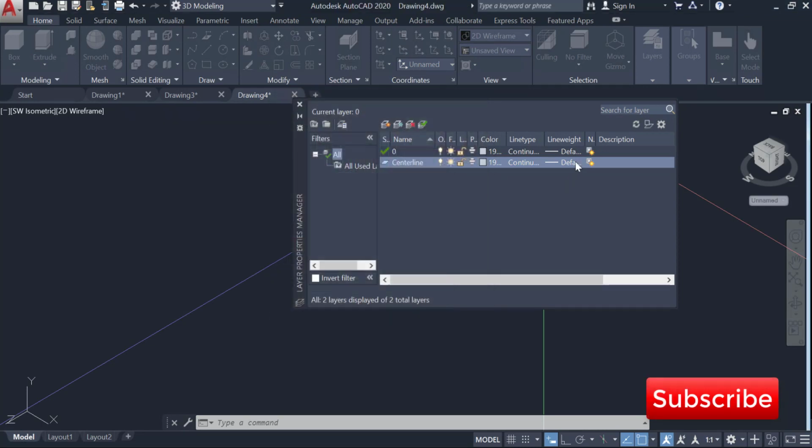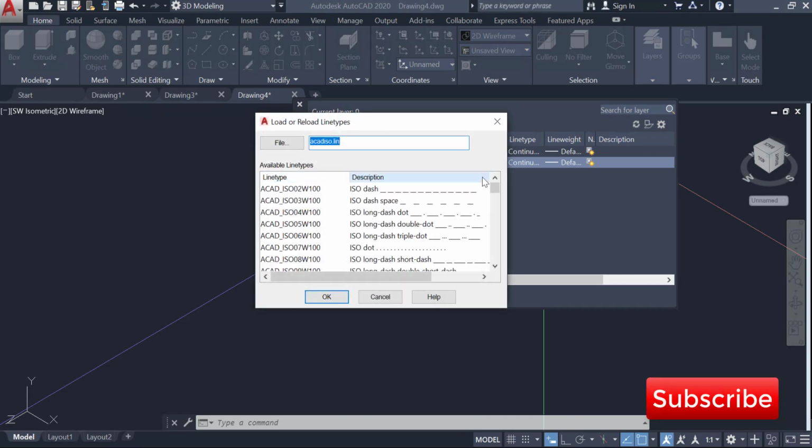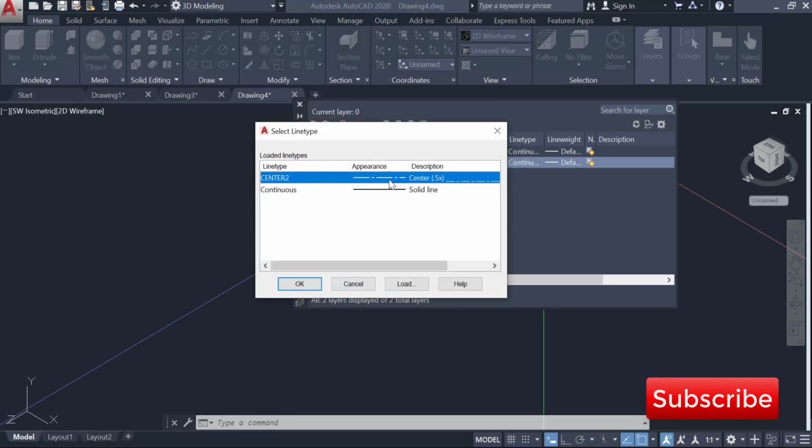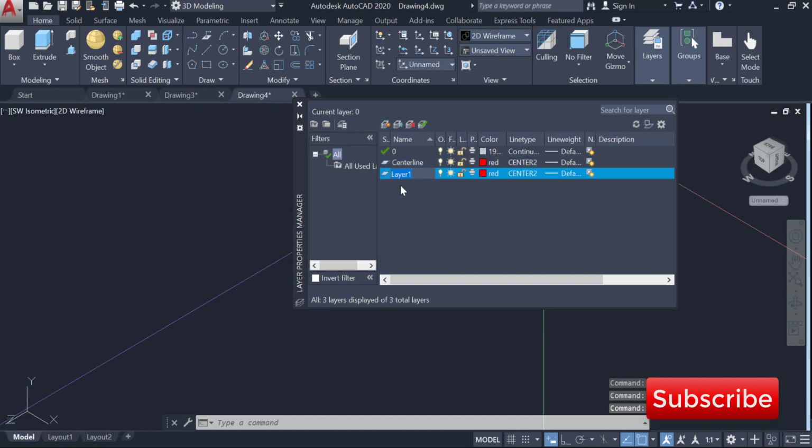You can use your own color. Click this line type, load the line types, select center 2, this one. Okay, I need to create another layer which is for dimension.